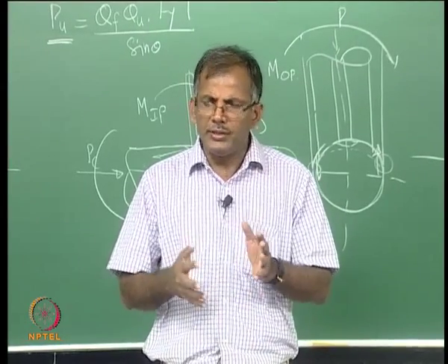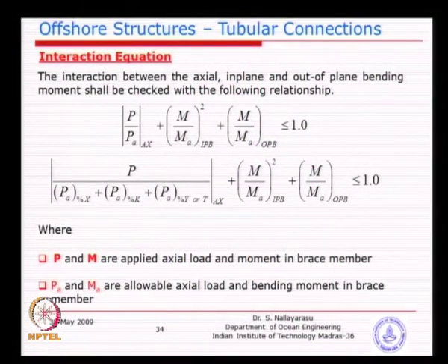But you see here, by this time you should have understood that joint classification has influence only on axial load, isn't it? Of course, the secondary effects you will also see, because when you go to the table for getting the values of QU, you will still select what type of joint, what type of load. But directly you can see here primarily the load path dependency is only on axial load, but not on moments.